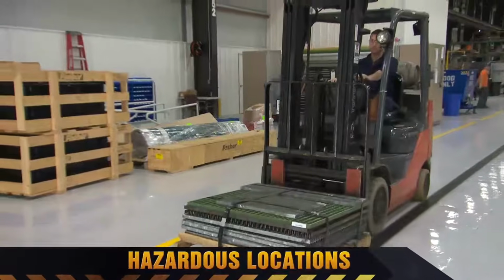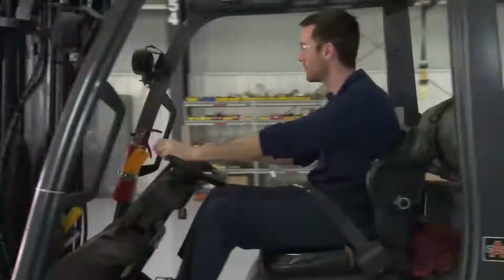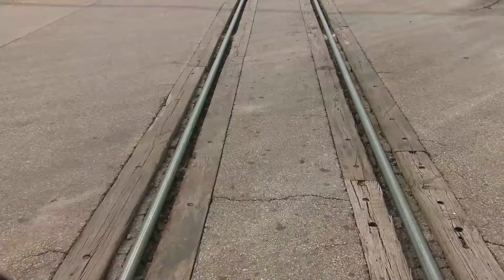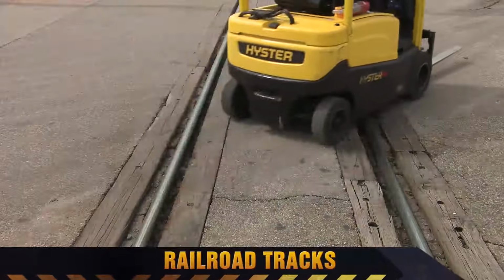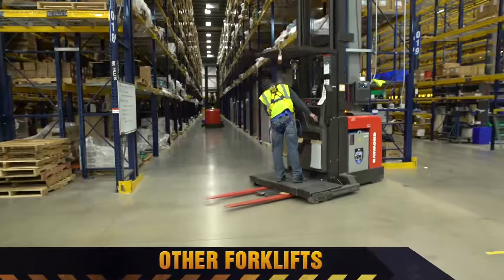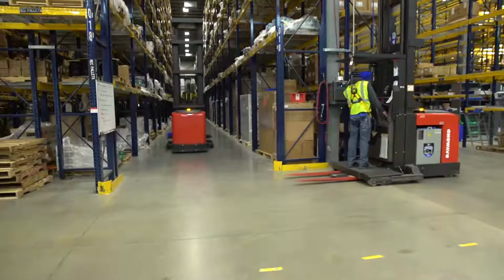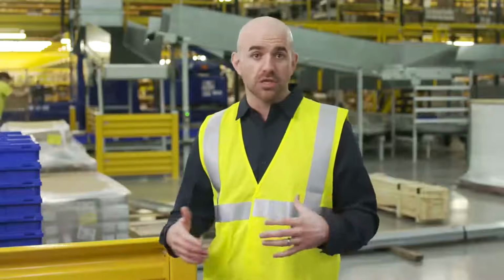There are hazardous locations also where chemicals or other hazardous substances are present. Choose the right forklift for the area to avoid fire or even explosion hazards. If you come across railroad tracks, take them on a 45-degree angle so you don't get stuck or shift your balance. Keep a safe distance from other forklifts. At least 3 forklift lengths in front of and behind you is a good rule of thumb. And don't pass other forklifts. The increased speed, intersections, and other hazards just drive up the chances of an accident.